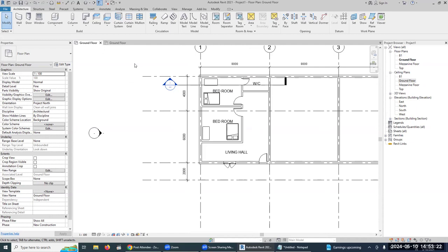If you go to that section, can you please come in? Section, take section here. Go to ceiling plan. Take section. The range, reduce it and go to view. So how do you go to view? Select on it, right click and go to view.